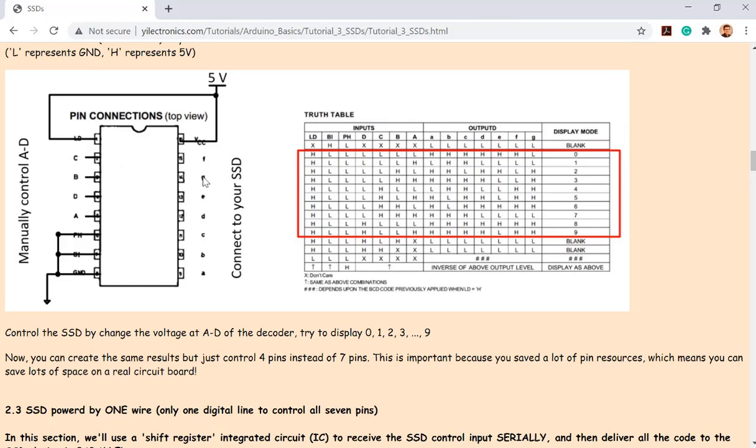So here's a decoder IC, right? How many inputs? Digital inputs. Is that 4? What are they? A, B, C, D, right? If you have 4 digital inputs, how many possible output patterns you may have? So the maximum amount of output patterns for a decoder for 4 binary bits input. 2 to the 4th, right? How many is that? 16. Okay.